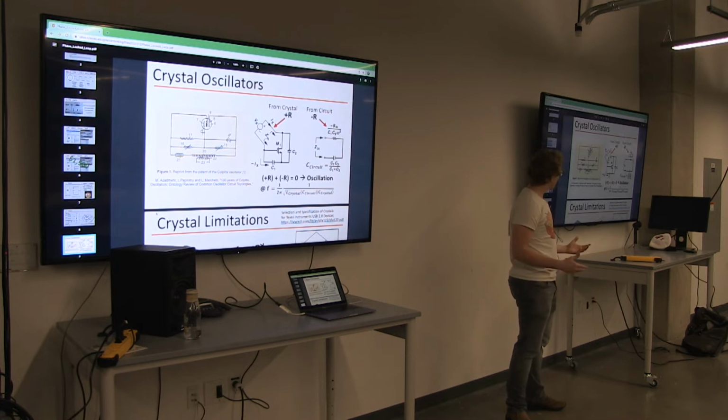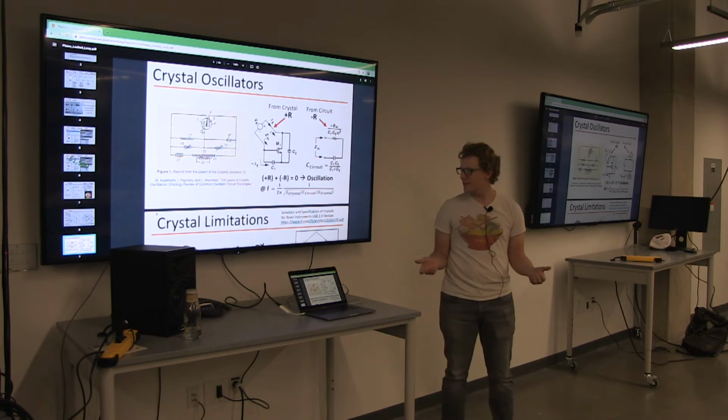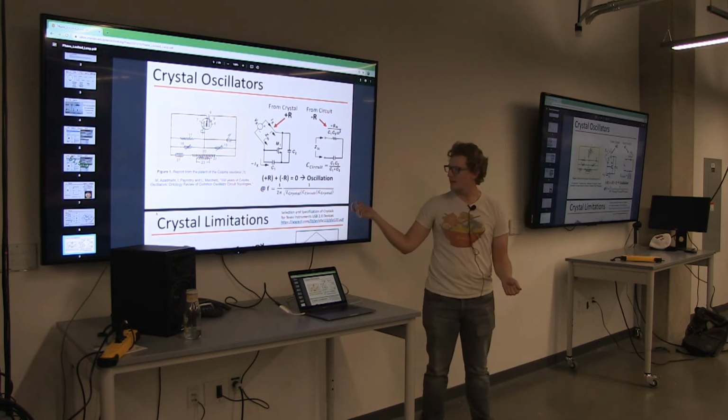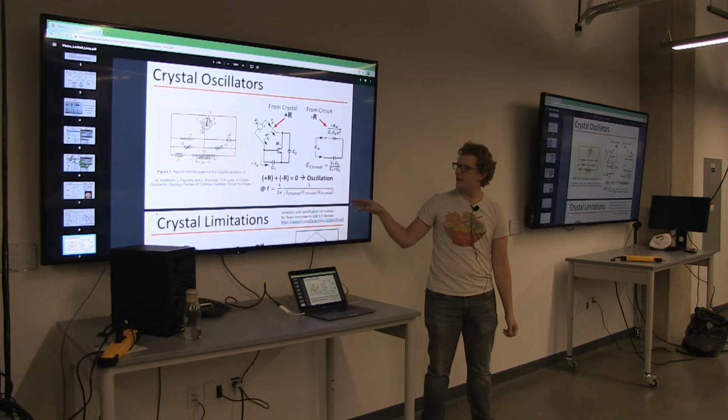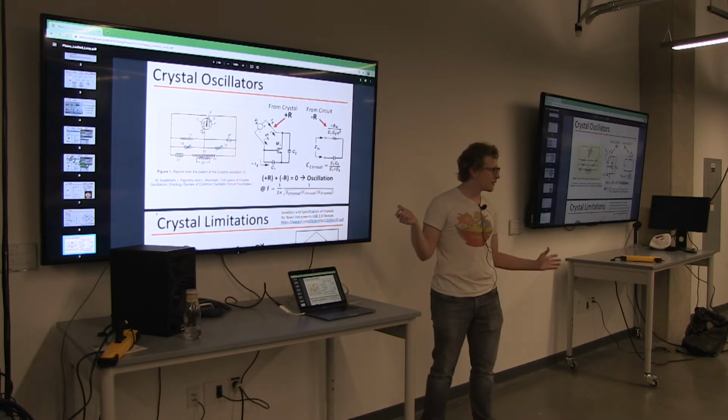And that allows the L and the C to resonate, and you'll thermally build up energy, and it'll start to get to an oscillator. And then the oscillation frequency is given by that LC network, and then we have to worry about a little bit of the circuit capacitance here as well. But usually data sheets for crystals will tell you to make this small compared to the C of the crystal. That way you don't have to care about it.